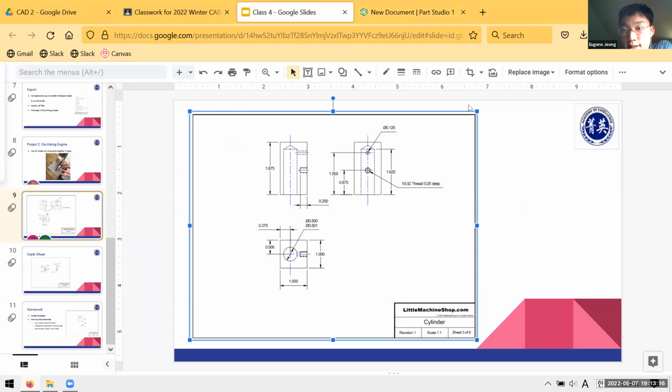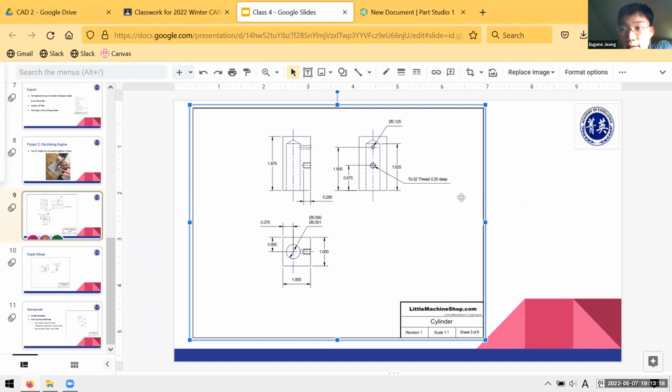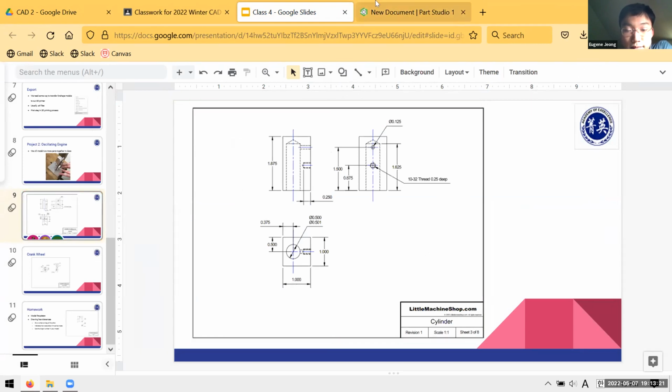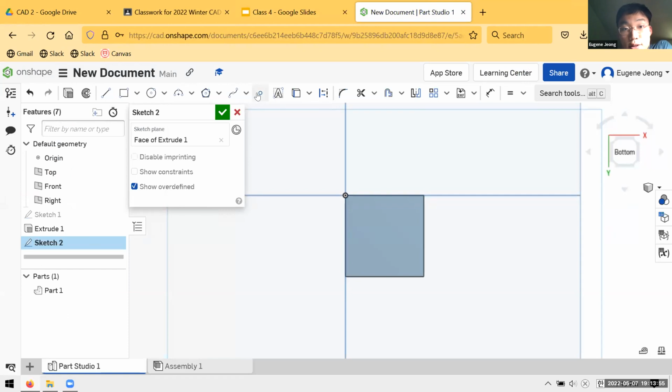And then I need to locate this hole. So what I'm going to do here, instead of creating a circle that I'm going to extrude with the remove option, that's how we've created holes up to now, I'm just going to create a point that's in the center location of the hole. You can see that there's a center line in blue that runs across here. And I can see that the center of the circle is 3/8 of an inch away from the left edge here, 0.375. So I'm going to create a point.